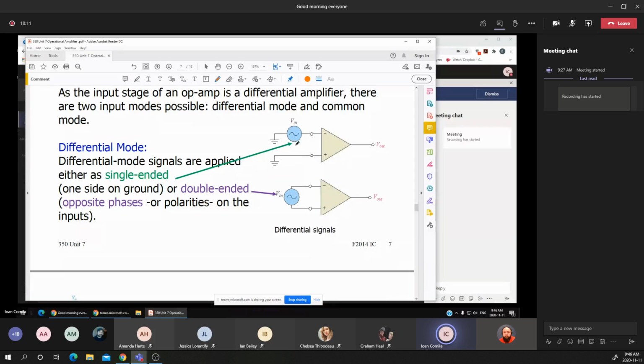Now we are doing the same thing. Suppose that we have the operational amplifier, and we are applying the non-inverting input to the ground, and we are applying a small signal as the V in into the inverting input. You notice that as the input is increasing, or is positive, the output will be negative.